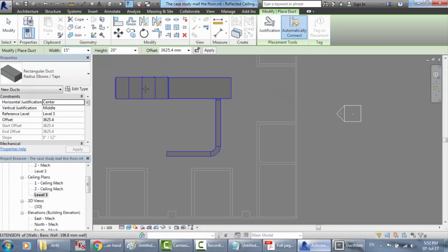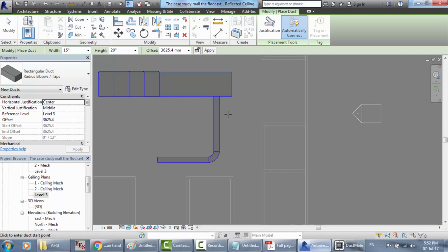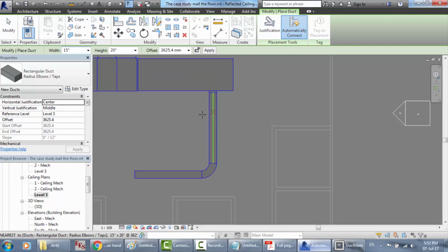So to sum up, we selected the air handling unit and set it in the right position on the roof. Then you have to determine the size of the main duct for this area, using the catalogs, the recommended feet per minute, the main duct, and the CFM.